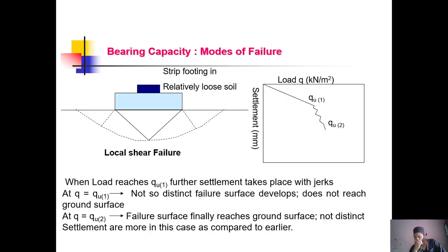It is very important that we know the different types of footings and foundations. While designing, we first design the slab, then go up to the beams, then the columns, and then the footings. In the design procedure we start with the slab and end up with the footing, but while executing, we start with the footing and foundation and go up to the slab. So it is very important that the foundations are strong enough to take accidental loading, unprecedented or unestimated load, when it comes.